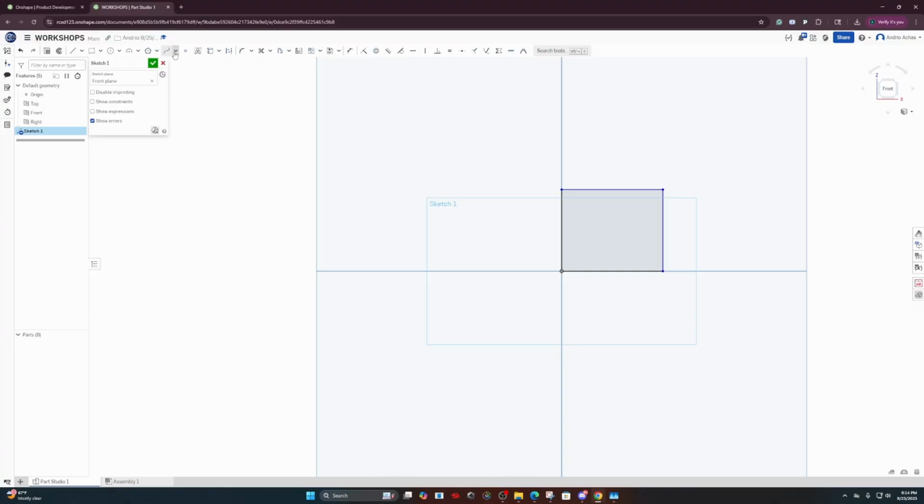Okay, then we're going to extrude it. So right now, let's go use the corner rectangle. The one you should be using is the one where you see there's a dot in the corners. If it's not that, let's say you use this one or this one, just press the bottom right arrow, it's like a drop down menu, and press corner rectangle. Or you can see that there's a letter right next to corner rectangle, it's G. That's a shortcut. So you can just press G and it should automatically select it or deselect it.